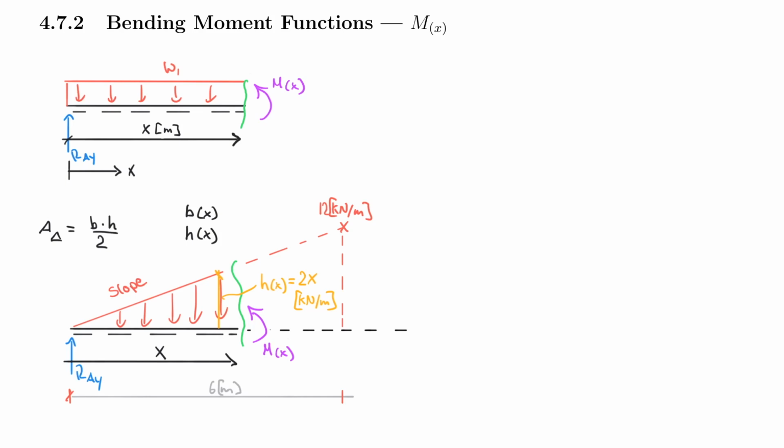And of course, you can probably do that already yourself based on what I showed you above, but let me develop it for you anyways. So I now will take the sum of the moments about location x, about this point. The sum of the moments about point x is equal to 0, counterclockwise positive. But let me clarify that this x here is the point x, so it's at a distance x from 0 here. It still really turns about the z-axis. We explained this in some previous lectures. You understand that a 2D moment really doesn't exist. A moment always rotates about an axis.